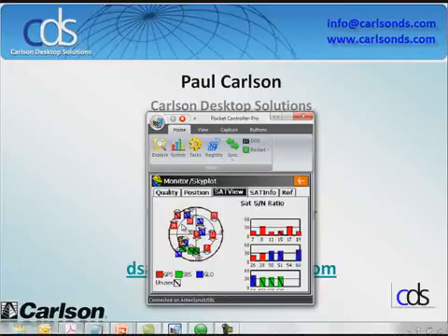The other thing that's in here are my satellites. Red satellites in my case are GPS, green are SBAS, and blue are my GLONASS. To the right, I can see all the signal-to-noise ratio values for each of the satellites, and I can see here and on the left which ones are being used. If they have a slash through them, they are not being used. Okay? What I notice here is that I have a bunch of GLONASS satellites with X's through them.